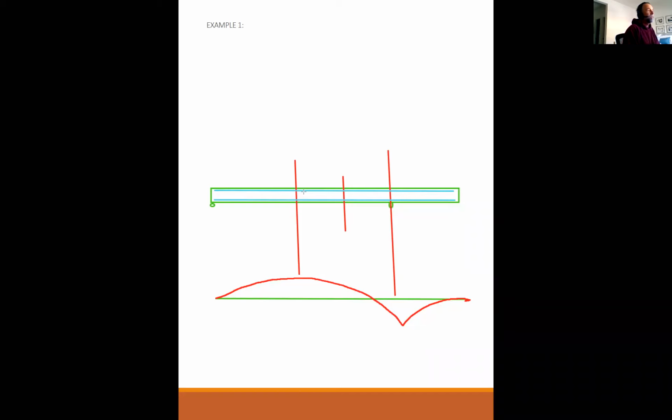Remember the lecture where we talked about compression steel? That compression steel only really helps you when you're pretty much maxed out on your tension steel, and you need to add more tension steel, but you can't because epsilon sub t is getting too small. That's when adding compression steel really helps. And then I did one example where I ran through the whole compression steel problem and compared it.